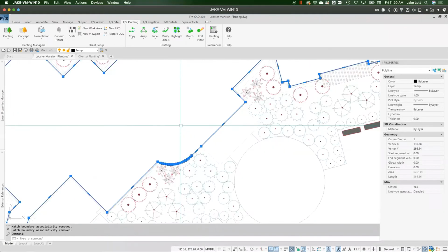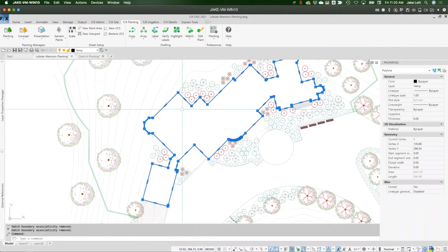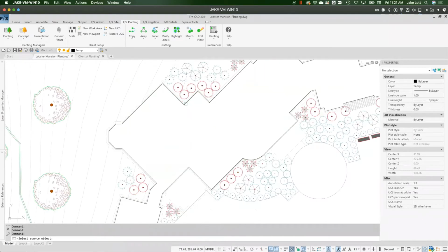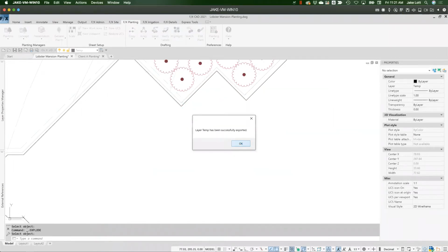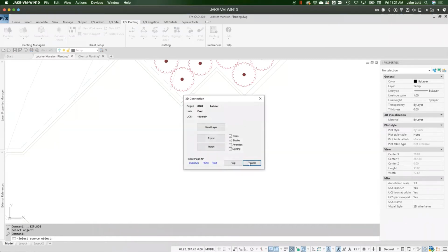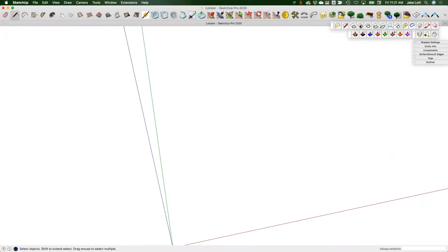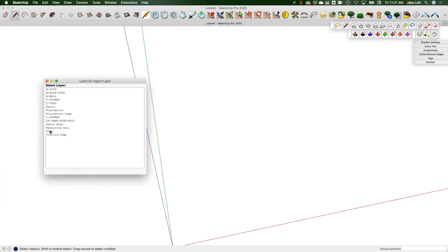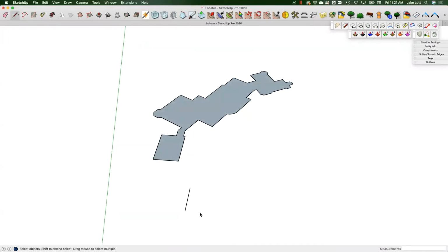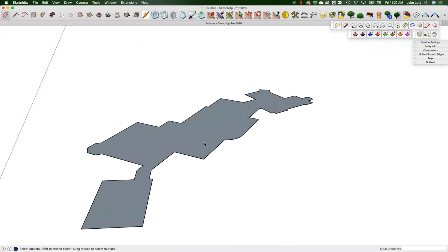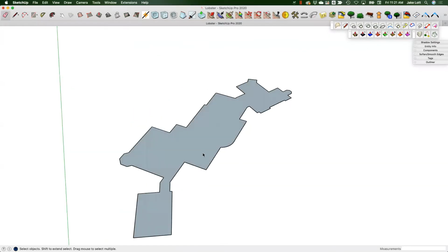I know now that this is a closed polyline. So why don't I send that layer over? So just thinking about these work smarter, not harder types of practices here. So I just sent that layer over. And now why don't we come over here and drop him over. And here's my temp layer. And there it was. Looks like I had another line somewhere in the drawing. But that already filled it out for me. So how easy was that versus the first way, right?